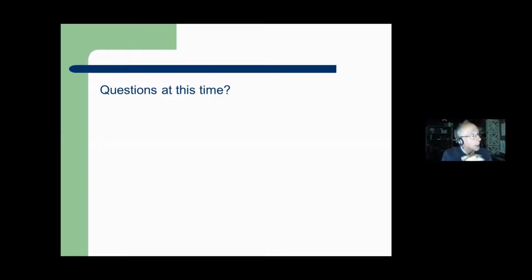If 6 meters, I'd say yes. And here's what Tim Duffy's K3LR's rule is. He doesn't want any more than 1 dB of loss. So guess what? On his 10-meter tower, he's got like 1 5/8 heliax. So he goes crazy. But it'd be nice to say 1 dB. On my 10-meter tower, I've got 2 dB loss, and I live with it. Okay, thank you very much. Sure.